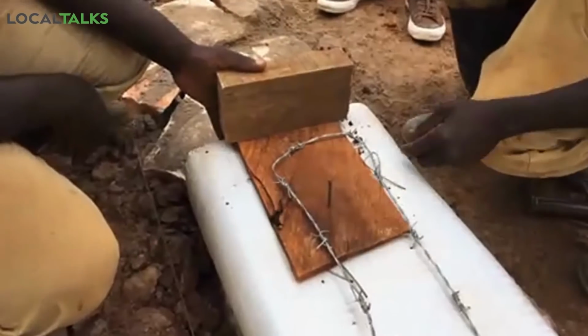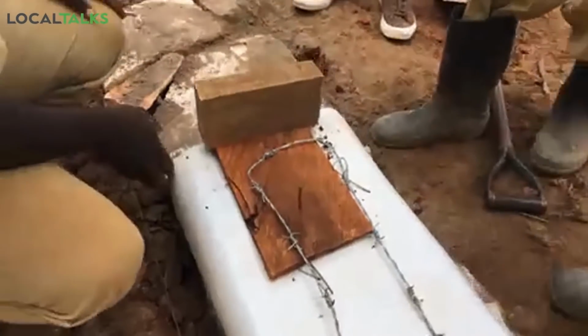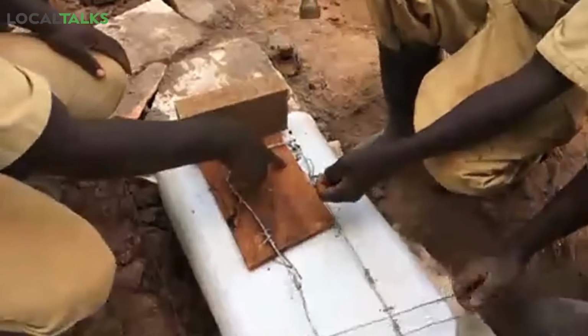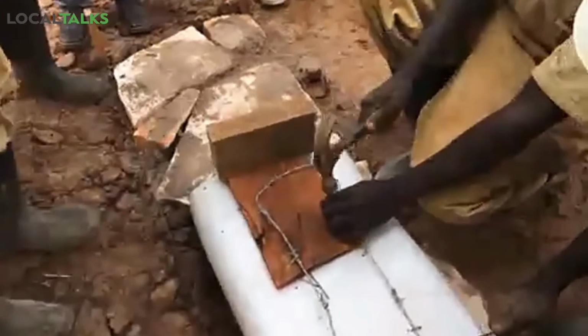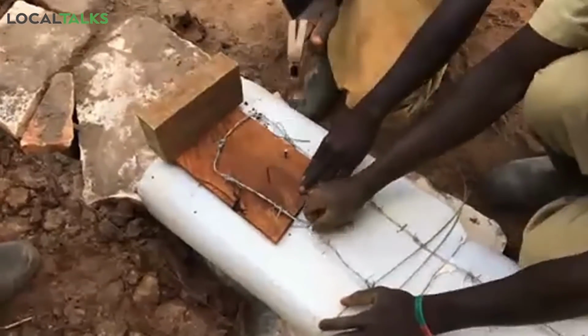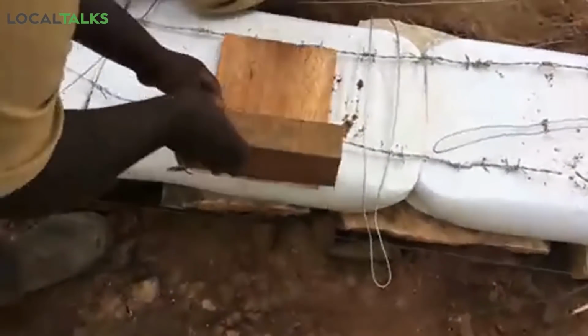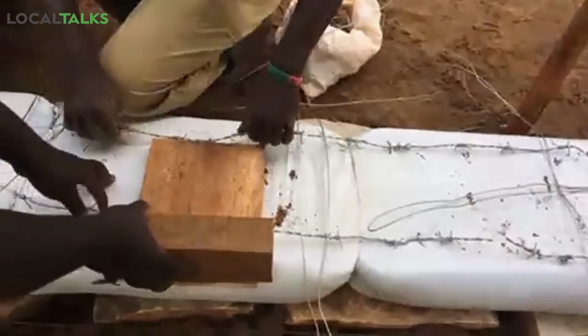This is just being held in place by a bit of nailing, but actually it is gravity, the pressure of the following courses, that will hold it in place. And then I think they have placed it flush on the door opening so that later any type of door frame can be easily fixed.